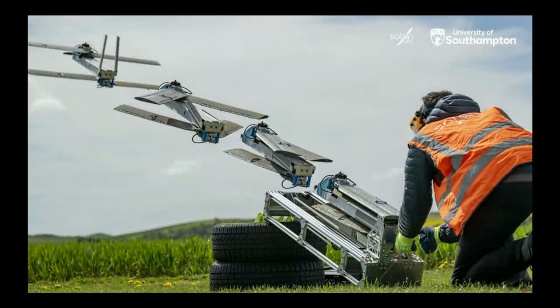And again, for another composite image of it taking off, we have this system. You can see that one of the tail fins is actually deploying a little bit too early, the second in from the left. That was just, I think, a slight flex in the structure, but it shows that these students were implementing delays to the ArduPilot system to make full use of it.